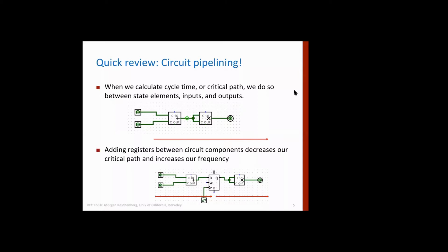Because when one stage is in operation, other stages remain unused. So throughput, or overall instructions executed from the system or data path, is just one instruction in one clock tick, which is too small, right? So a better thing is, why not use the parts which are unused with the concept of pipeline.